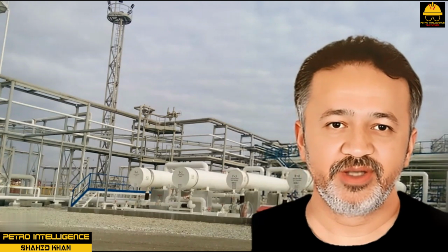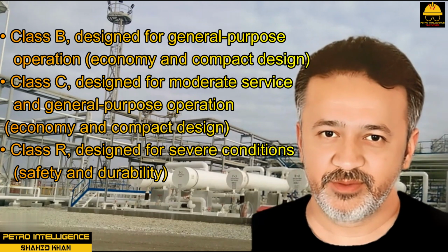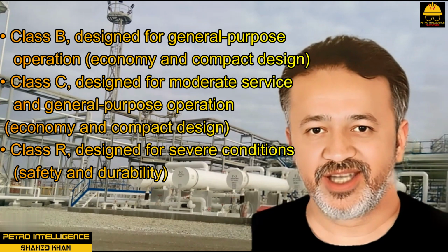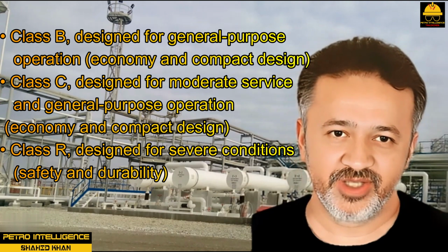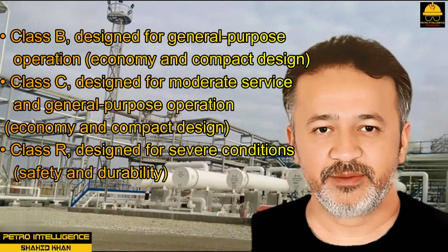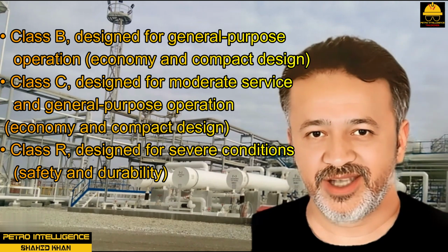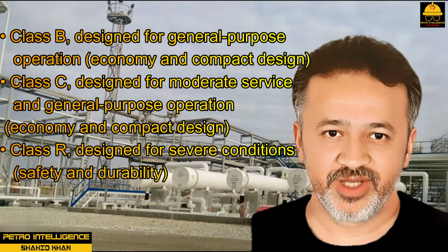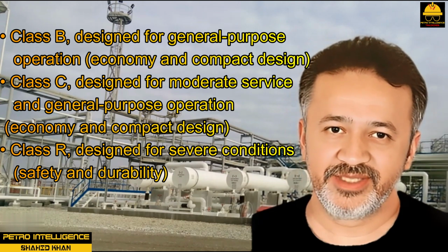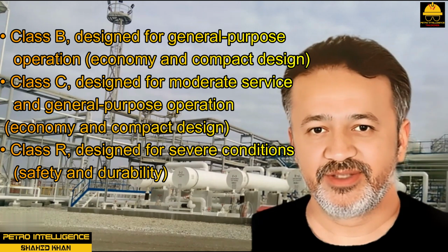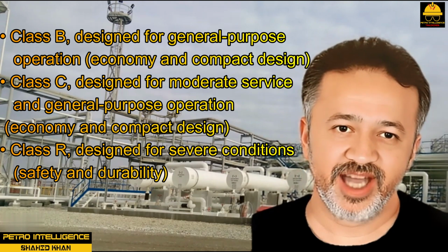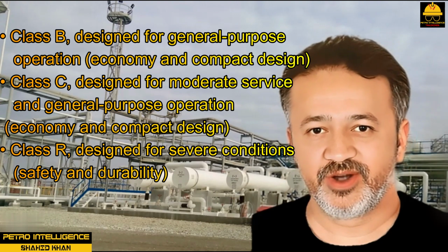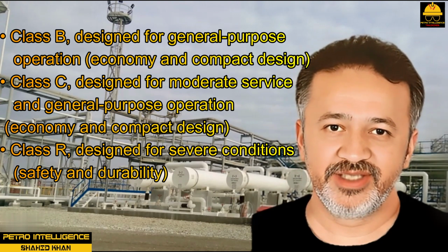The Tubular Exchanger Manufacturers Association, TEMA, classifies heat exchangers by a variety of design specifications, including American Society of Mechanical Engineers, ASME, Construction Code, Tolerances, and Mechanical Design. Class B, designed for general purpose operation, economy and compact design. Class C, designed for moderate service and general purpose operation, economy and compact design. Class R, designed for severe conditions, safety and durability.